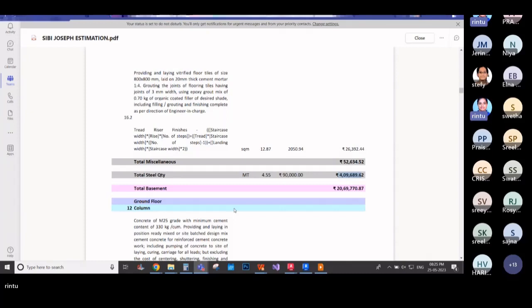Now that was about the cutting and bending part. As we saw in the video, when the person is working with rebar bending manually, he has to use a lever and a 3-pin in order to bend the rebar. This is a lever, which is used for applying the force in order to bend it. And a 3-pin is just a small device used to help bend the bar in the required angle.